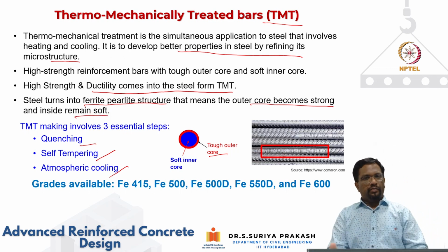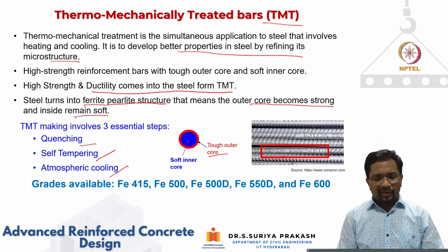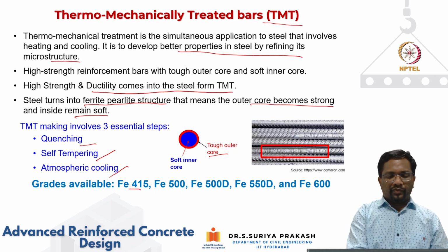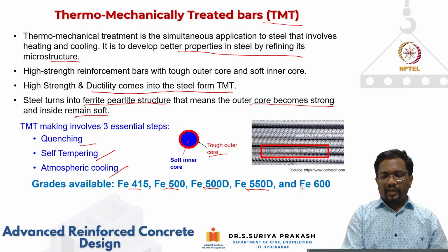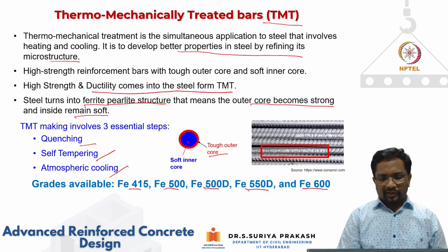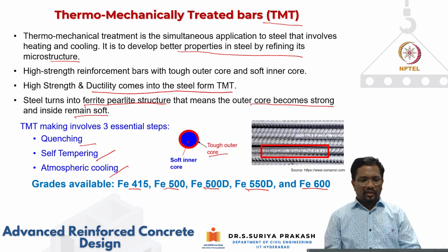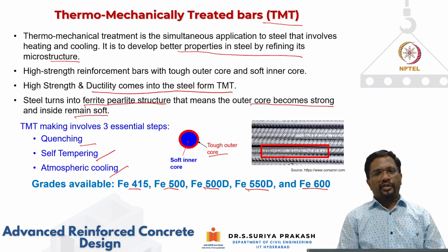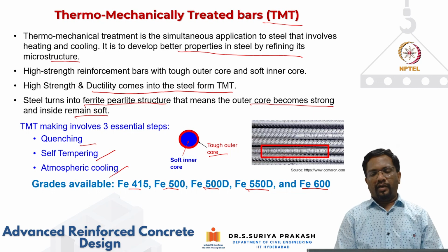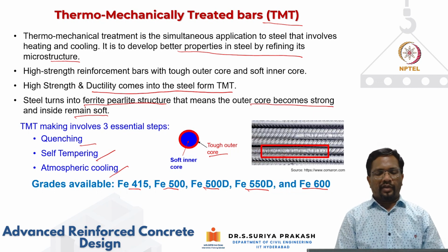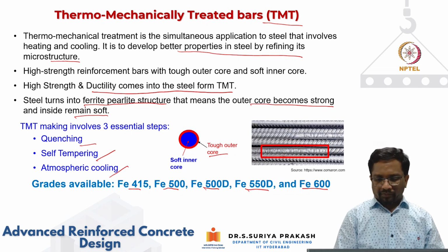Okay. So you have multiple grades available in TMT rebars. One is Fe415, Fe500, Fe500D, Fe550D, and Fe600. So again, D stands for ductile. For seismic applications, sometimes we use Fe500D or Fe550D, depending upon the requirements.